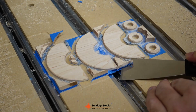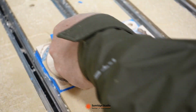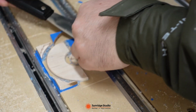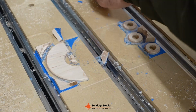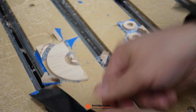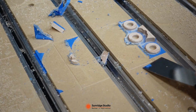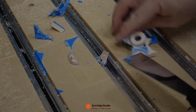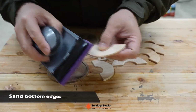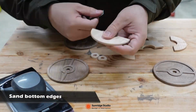After the CNC process, I just light sanded the pieces, mainly the bottom edges. After dry fit, I glued them together with Titebond 3. Then I sanded the top and bottom surface to 150 grit and cleaned up with mineral spirits. After the mineral spirits dried in about 4 to 5 hours, I applied 2 coats of Rubio Monocoat.